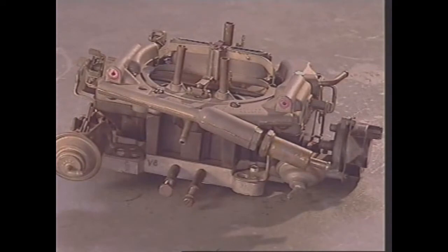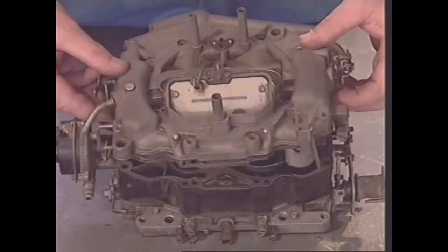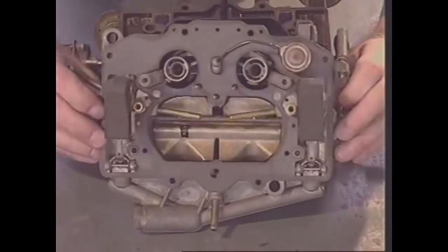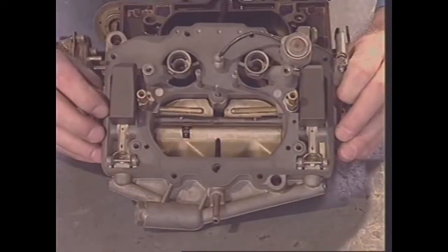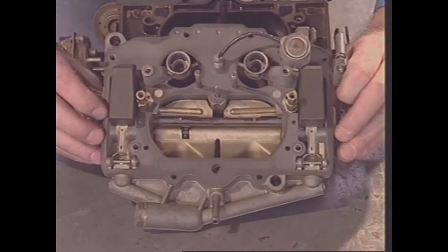Large capacity V8 engines may use a 4-barrel carburetor of 2-stage design, effectively 2 2-stage carburetors combined, with each side supplying 4 of the 8 cylinders. A central moulded plastic fuel bowl and suspended metering system can be incorporated into the design. This gives lower fuel temperatures with more precise fuel metering and closer control over air-fuel ratios.